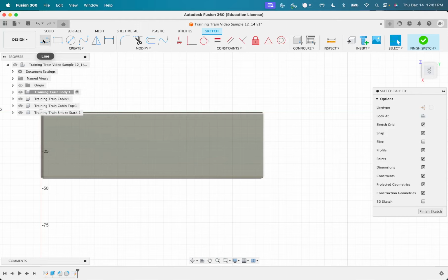So to create a line, we can just go up in the top left, select the line. And for the construction line that we're going to create, we want to just click somewhere below the body itself and then just make sure that it stays 90 degrees. So make sure the degree you can see is 0 or 180, and then just click somewhere past it. And then once you've done that, it'll ask you to create another line. You can just hit escape to get out of that.